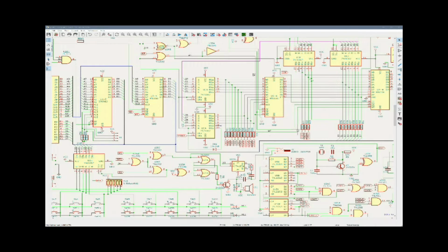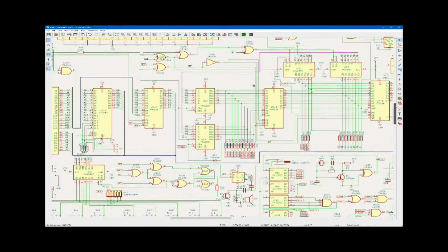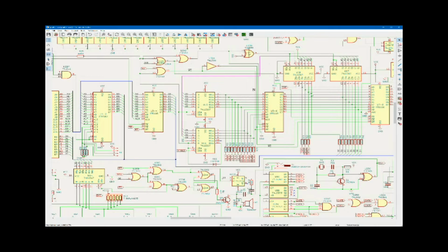Now if we look at the address lines, they're coming from these 74LS367s up here. Going up a little more, they're getting triggered by this XOR gate, which is coming from this other gate. If we think about the timing, the write enable gets triggered off of this gate.